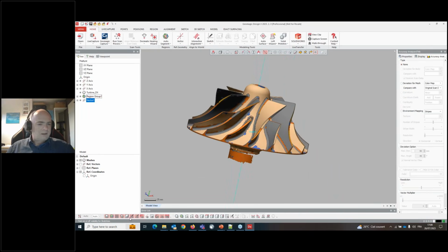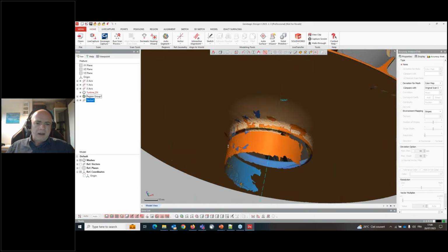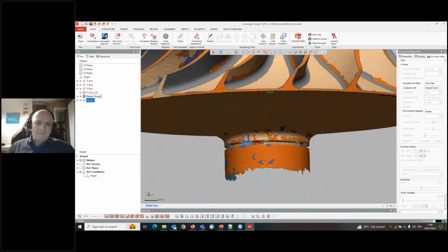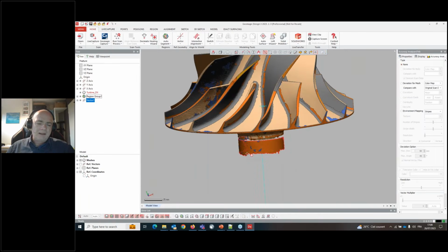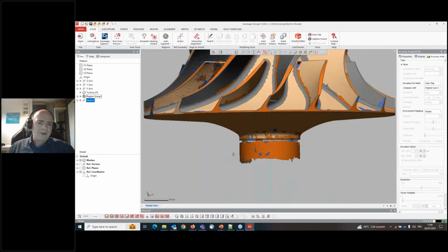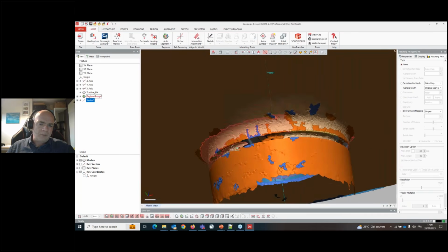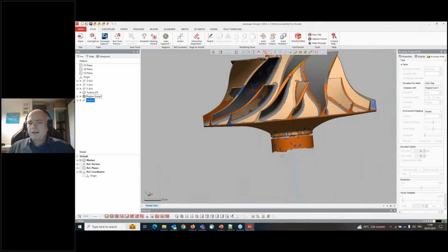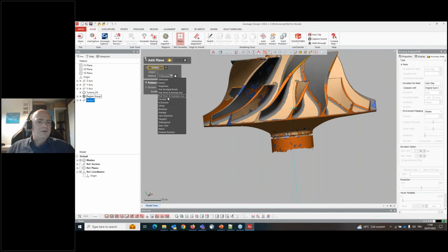So now this axis is done. Maybe I can also use, well, that's the axis. I need a plane to define my origin. Maybe I can use the plane which is defined in this area, or a point over there, or maybe I can extract the minimum point in this direction. So to do that, I will extract a plane, and I will ask the software to extract here the extreme position. The entity is going to be the mesh, and the direction is going to be the vector.